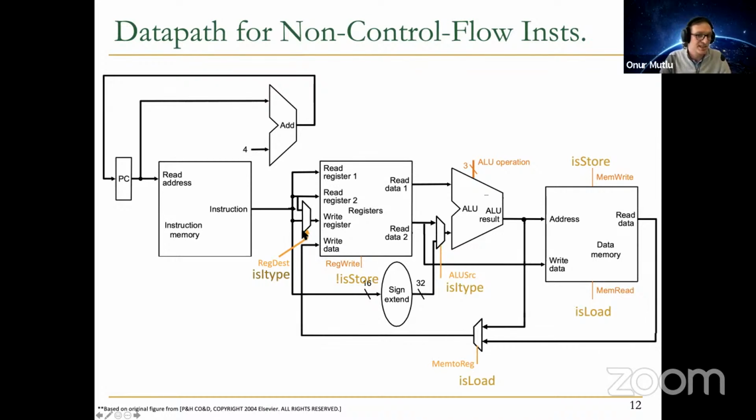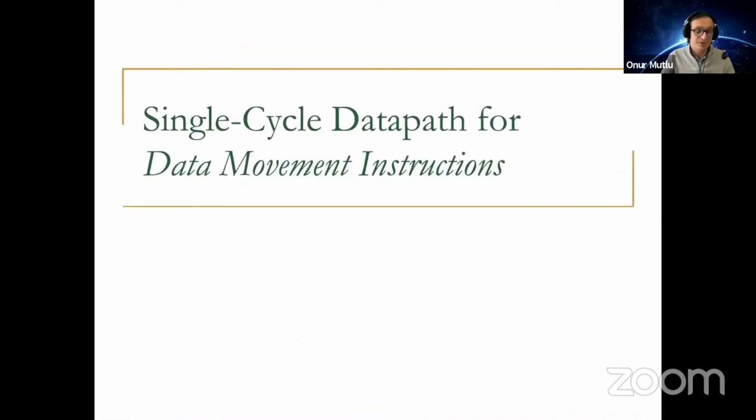And the destination register is selected by some bits in the instruction, and load word happens to be an I-type instruction, if you remember, and that needs to select the top input over here. Anyway, for more detail, look at the previous lecture, but I just imitated how a load word executes on this data path that we built last time and how the control signals need to be set.